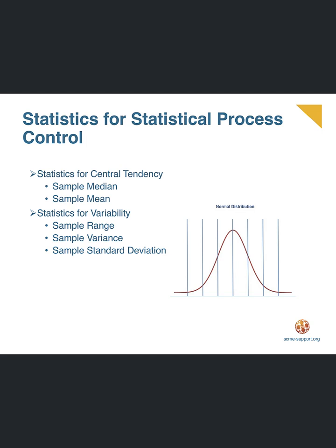These concepts are used to provide basic analytical descriptions of data. Most often in manufacturing, statistical analysis is usually done on a sample of data. So the statistics that we will cover here will be for a sample set of data. All calculations will use the data from the sample. The statistical calculations include sample median, sample mean, sample variance, sample range, and sample standard deviations. We will briefly discuss these statistical concepts that you will need to understand in order to employ SPC.